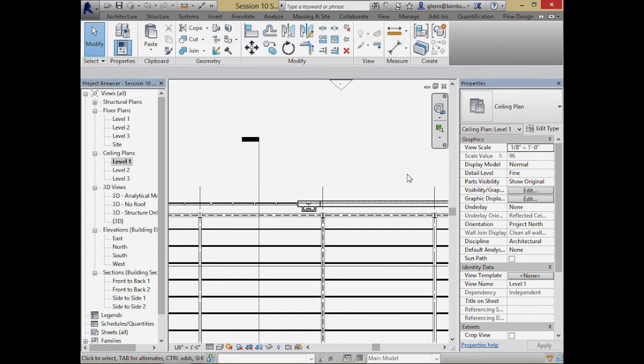For the people who are doing the structure inside the facade, are you doing steel or concrete? Concrete. Okay. You like concrete. It's actually a very good material for what we're trying to do here. Steel or concrete? Steel? Yeah, very good. Concrete and steel, it's almost a funny choice. In different parts of the world, concrete's incredibly common because steel is very, very expensive, concrete's relatively inexpensive, and concrete has fantastic thermal properties, though it requires a little bit of quality control in the field. There are all these trade-offs. It's often local conditions and economics that determine whether we go with a concrete or a steel building.